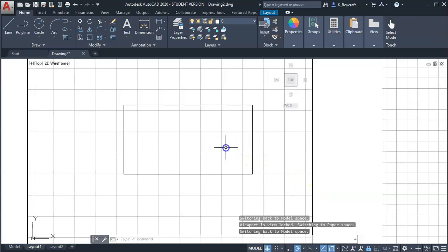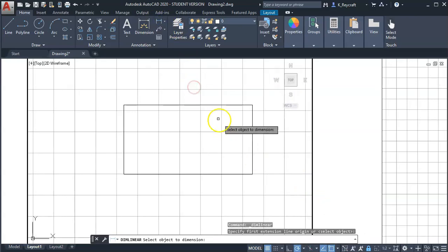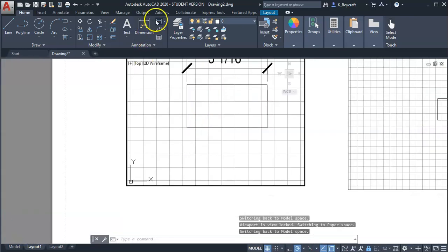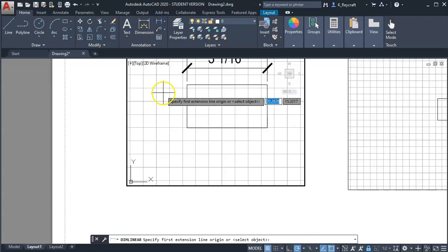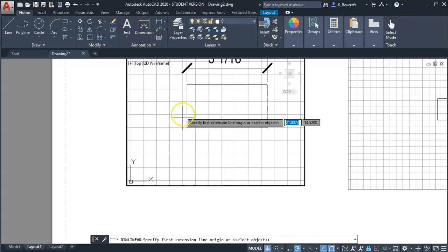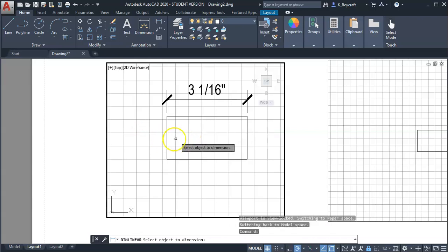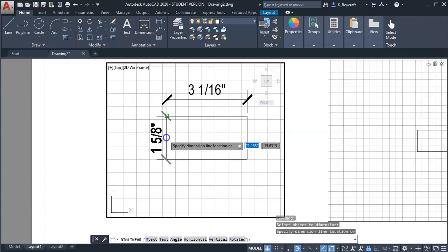All right, so going back to this viewport, I'll add some dimensions. And by the way, what I'm doing here is I go to the linear dimension command. If I know I'm dimensioning a line, this one object, I can right click rather than picking each line, and then I can just pick the object I want to dimension.